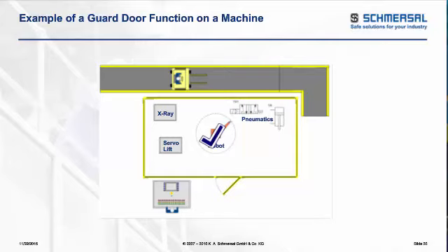It's wired up properly. We now look at our elevator lift, and we say, okay, with the elevator, we have a servo drive that has the safe torque off. We set up the software parameters for that to do a dynamic braking to get it to stop as quickly as possible and provide a safe condition, not allowing that elevator lift to move when that door is opened.